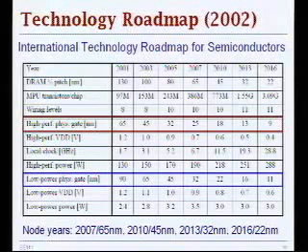And in order to sustain the performance, you would have to operate with higher supply voltage, but also you have higher threshold voltage to be able to work with this standby power consumption problem. And in the high performance cases, you want to deliver as much computation as possible over a period of time. Leakage will be a problem there as well, but as long as you are plugged into the wall and your chips are not melting for power density reasons, you're fine. You'll just pay a higher electricity bill and you'll still do your job very efficiently.